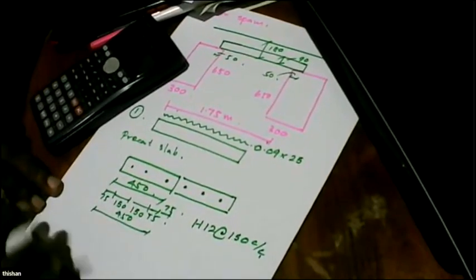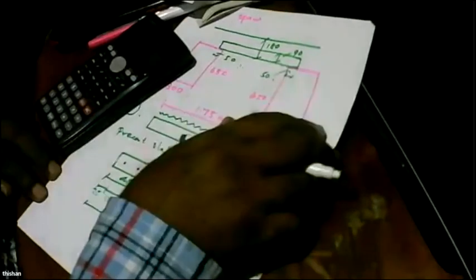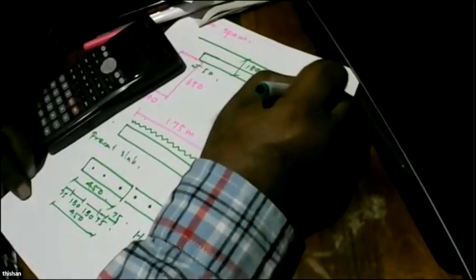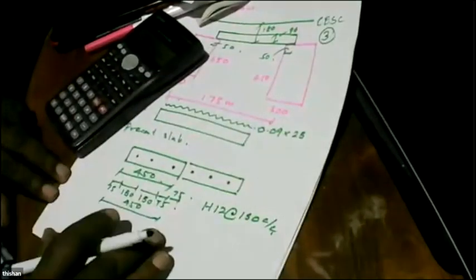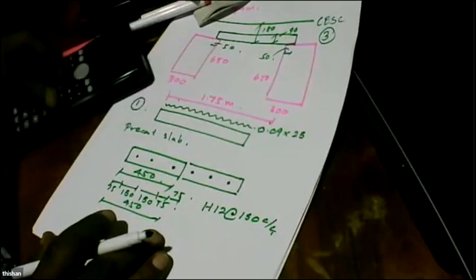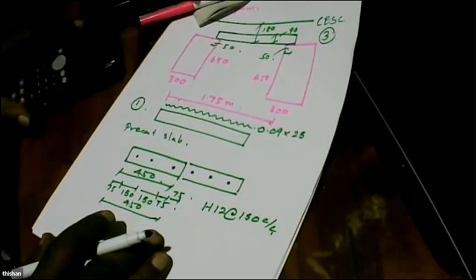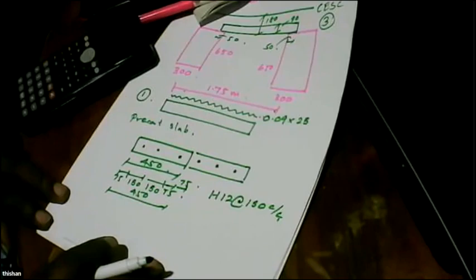So that's why we prefer this 450 millimeter width, because when you place the reinforcement, you can place it at 150 center to center. But depending on the reinforcement requirement, you can change the diameter. Again, you will ask why 150. Bridge engineers have been very comfortable with this 150 millimeter spacing for bridge decks. It's something that they have developed traditionally.